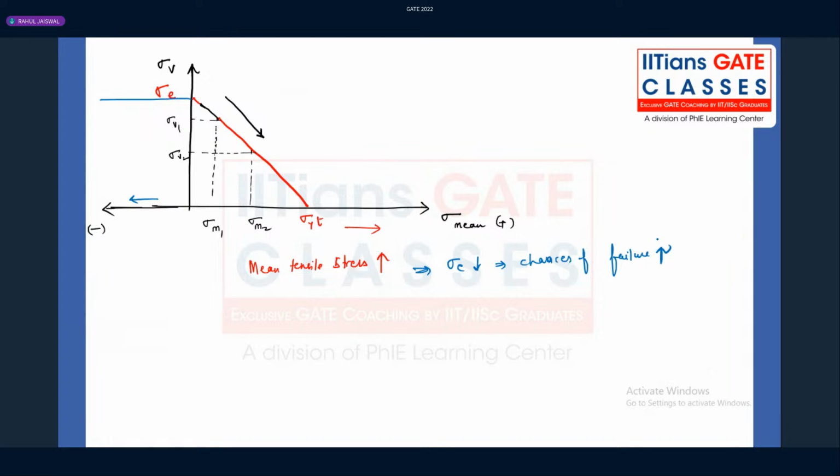Now, what are the best methods we have? We have cold working, we have surface treatment. What are the surface treatment operations we have, like nitriding, carburizing, case hardening. On the basis of this treatment, we can decrease the cracks, because everything depends on cracks. Whenever there is a crack, when you apply the tensile force, this crack will elongate and become larger and larger. The material becomes too sensitive to the crack, and the moment you start rotating that material, it will fail. That is what we call a fatigue failure, right?